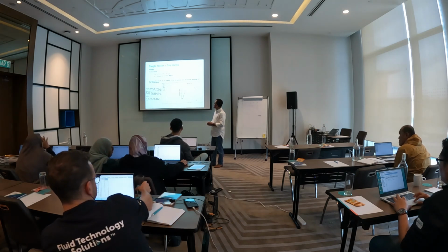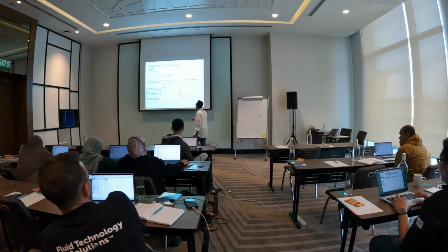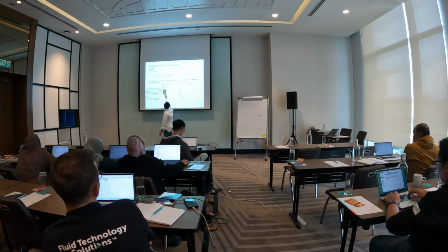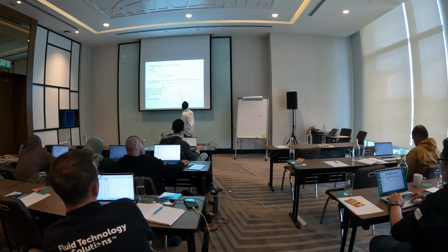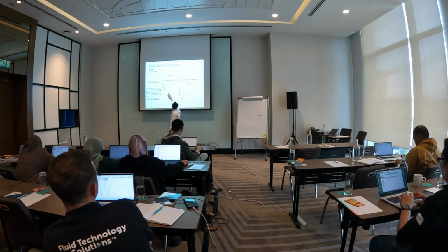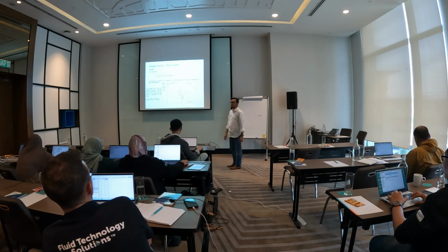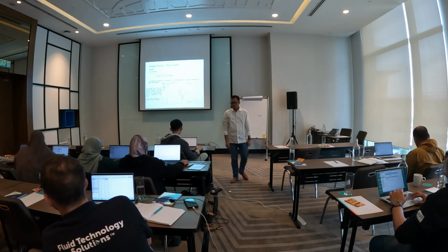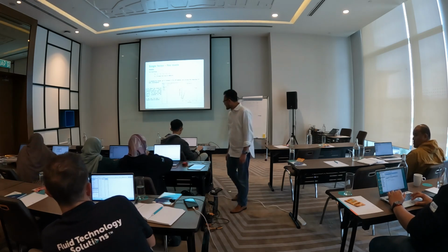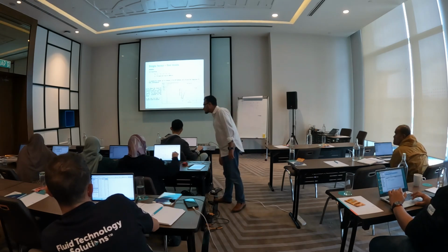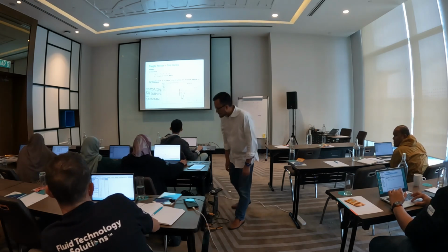So to analyze the result, we can go to the analysis. This one, and then on the left sidebar, you can choose response R1, battery life analyze. You can choose this one, analyze, and then you can see the effect on the tab. If you click, in the new version of the software, you need to select a transformation first. So in this case, you choose no transform, that's the default option, and then you click start analysis.